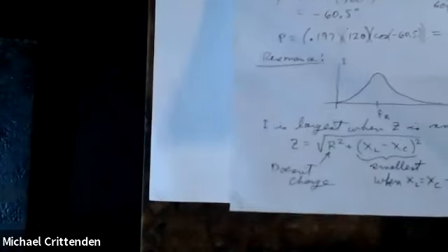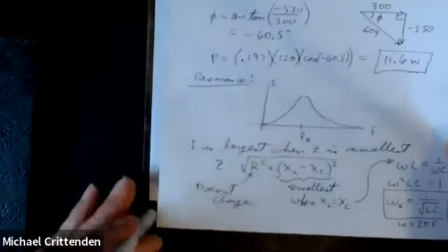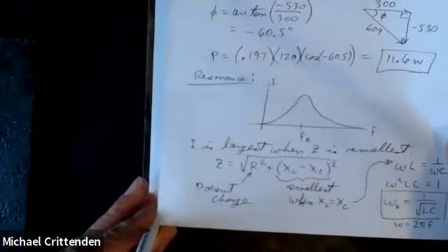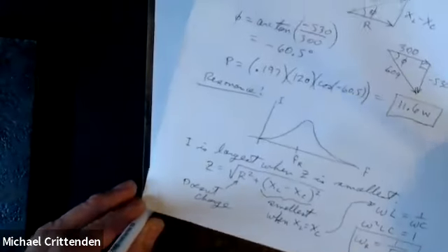Like if I have these two sheets of paper here, if these are two metal plates, and let's say I have the corner of them mounted on a metal rod like that, and there's a knob on the end of this rod. When you turn the knob, it makes the one plate rotate like that, so that the farther you turn it, the less area there is in between the two plates. That will change the capacitance. Actually, they have a whole bank of plates instead of just two of them, but that is how you can make a variable capacitor.